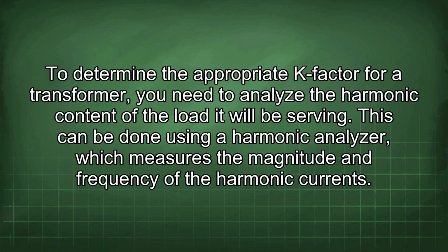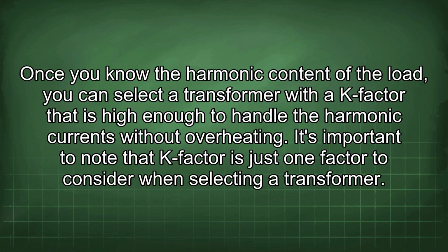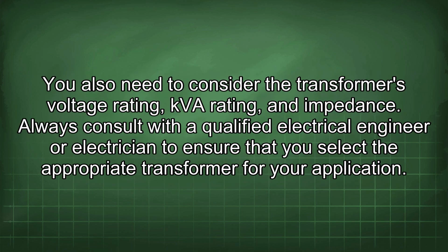To determine the appropriate K-factor for a transformer, you need to analyze the harmonic content of the load it will be serving. This can be done using a harmonic analyzer, which measures the magnitude and frequency of the harmonic currents. Once you know the harmonic content of the load, you can select a transformer with a K-factor that is high enough to handle the harmonic currents without overheating. It's important to note that K-factor is just one factor to consider when selecting a transformer. You also need to consider the transformer's voltage rating, kVA rating, and impedance. Always consult with a qualified electrical engineer or electrician to ensure that you select the appropriate transformer for your application.